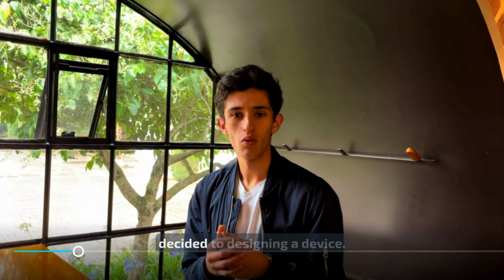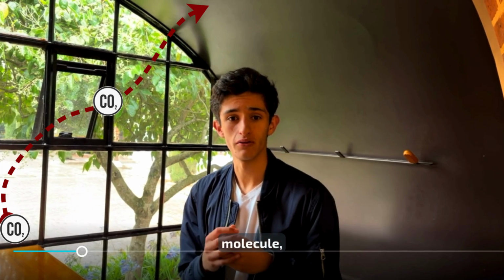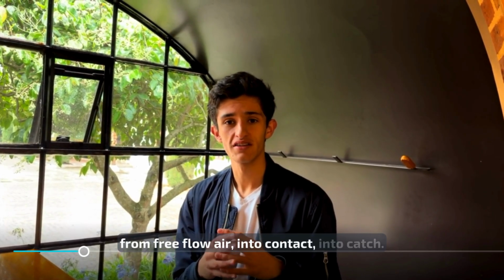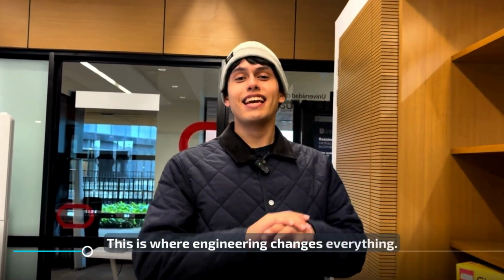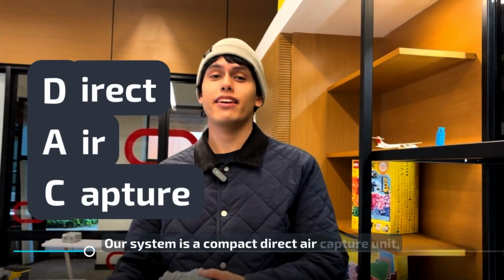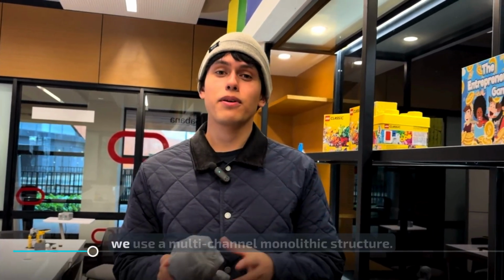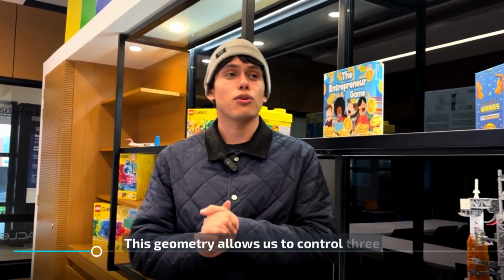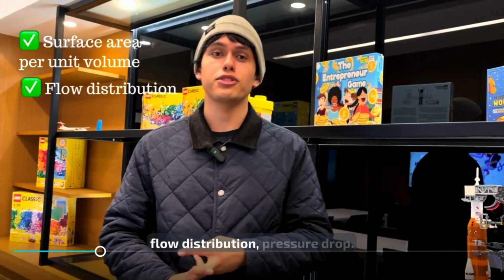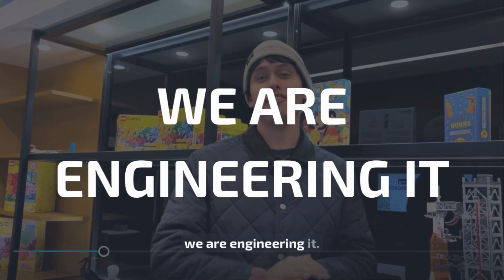So we changed our approach. We didn't start by designing a device. We started by designing the journey of a CO2 molecule, from free flow air into contact into catch. This is where engineering changes everything. Our system is a compact direct air capture unit, designed within a 1 cubic foot constraint. At its core, we use a multi-channel monolithic structure. This geometry allows us to control 3 critical variables: surface area per unit volume, flow distribution, and pressure drop. We are not waiting for contact to happen, we are engineering it.